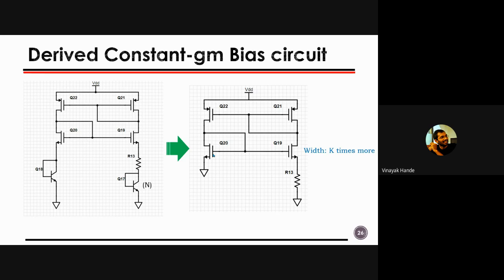And this is nothing but a VDD independent circuit, meaning the currents are the same in both the branches, and both the currents will be independent of VDD variation. Mind you, this is again similar to PTAT, derived from the PTAT circuit itself, so the current is not independent of temperature, it increases with temperature. So it is a kind of CMOS based PTAT current generator, you can say. Because it is nothing but delta VGS by R. Previously, it was delta VBE by R. Nothing has changed.